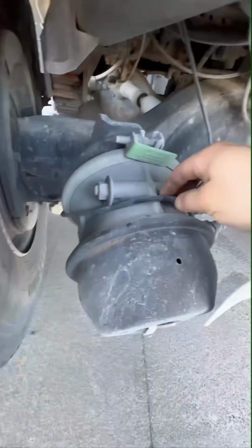Customer states, my car has been shaking like crazy. They already checked my tires, rotated and balanced them several times, but still no change. Help. Come over here. Let me show you what's wrong with this car. If you notice, it has universal wheels, so they're not specifically made for this car.